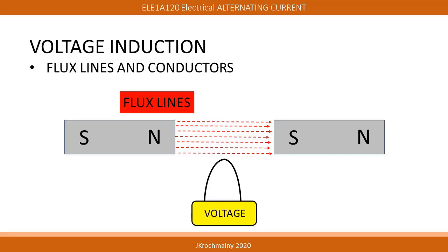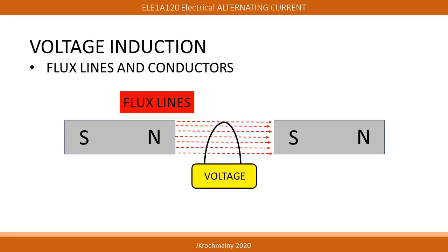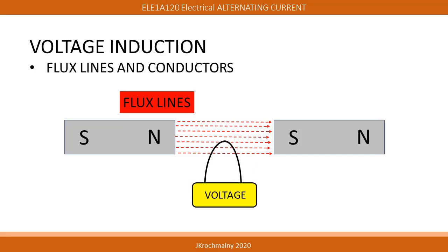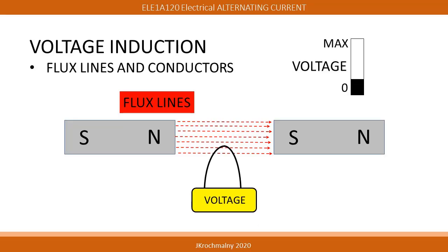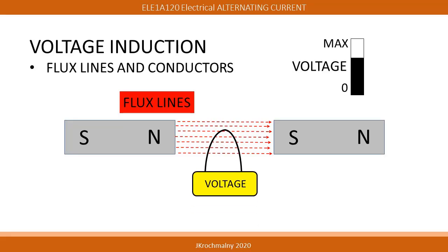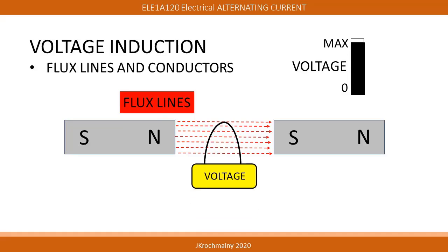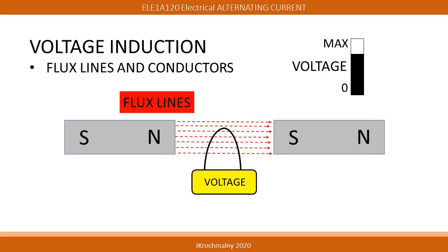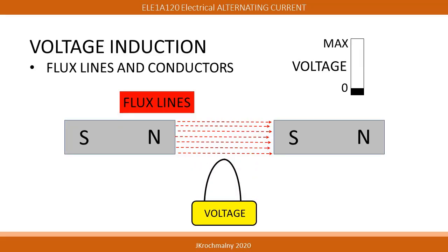He took a voltage meter and started to measure the voltage induced into the meter leads as the leads were passed through the magnetic lines of flux. Faraday discovered that voltage was induced into the meter leads and read by the meter whenever the leads were passing through the flux lines. The greater amount of flux lines being passed through the leads, the greater the amounts of voltage pressure were measured. This phenomenon is called voltage induction, the conversion of magnetic energy into electrical energy.